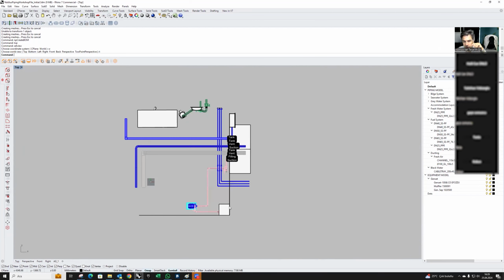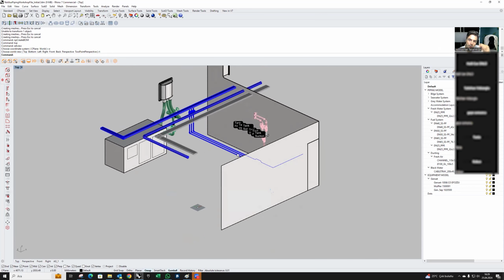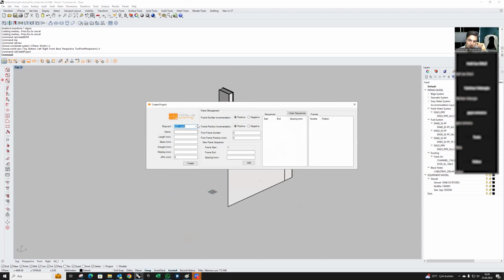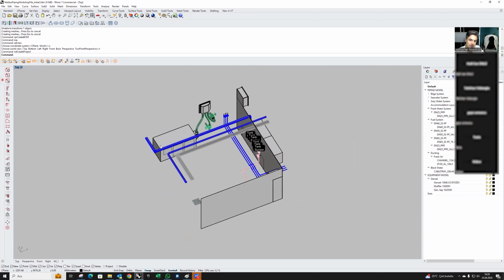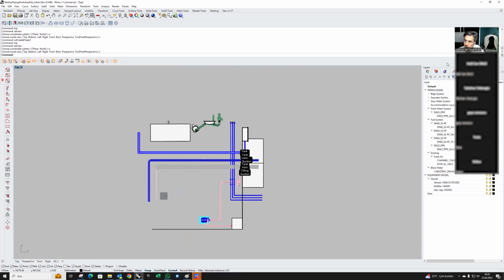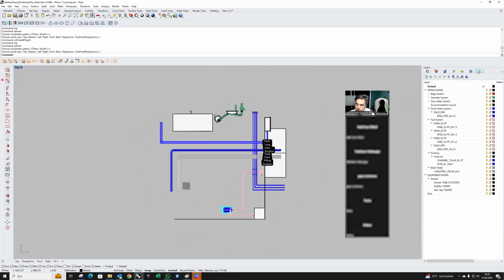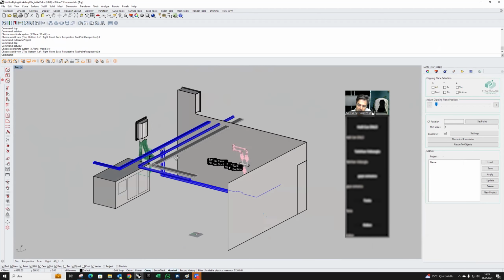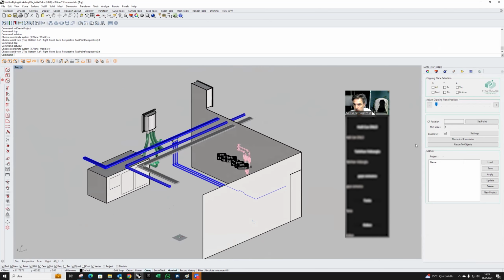So after creating this model, we can do the workshop drawings with Nautilus Drafting. And here you create the project with these parameters, and afterwards you select it as active. Once you create the 3D model and the project, you simply go to the clipping plane tool here, and you start to save the views that you want to include in your drawing.